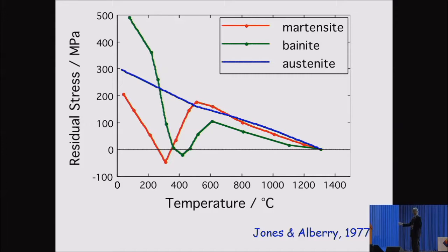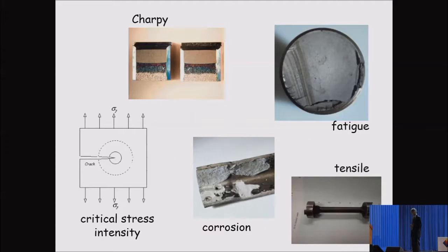Now, they were studying some other phenomenon, not trying to design any welding alloys. But when we design any welding material, it doesn't just compensate for residual stress. It has to have a whole combination of other properties which are good for the joint. For example, everybody knows that the Charpy toughness has to be acceptable, and the fatigue strength has to be acceptable, corrosion resistance and crack growth rates, everything.